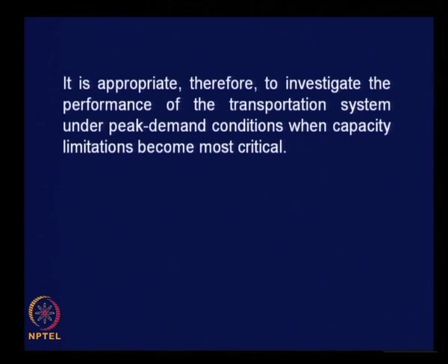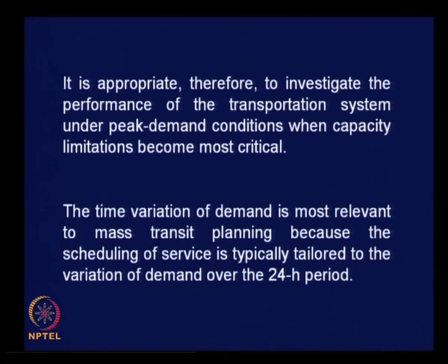So, you just check the capacity of the system when the demand is high during the peak period. The time variation of demand is most relevant to mass transit planning because the scheduling of service is typically tailored to the variation of demand over the 24-hour period. This is the most important point.